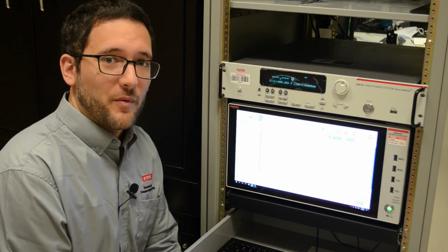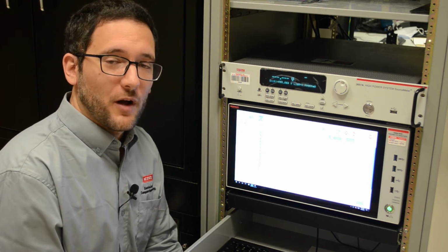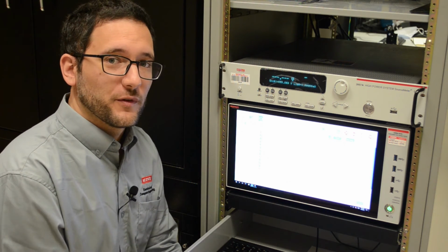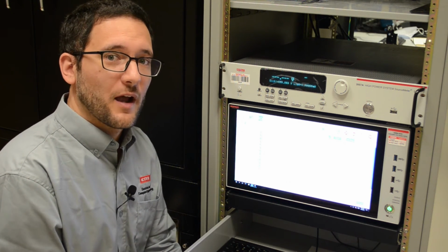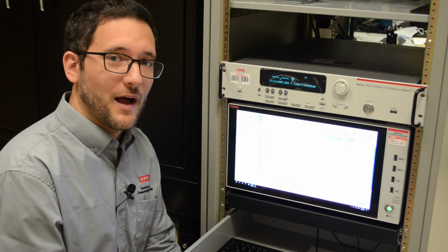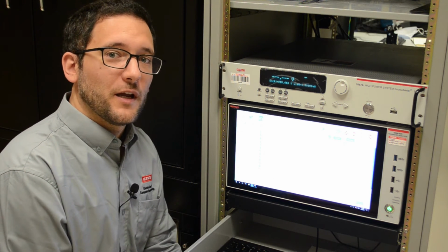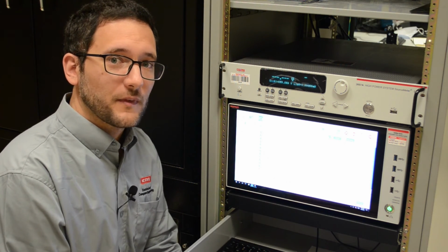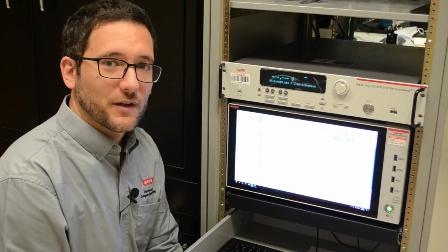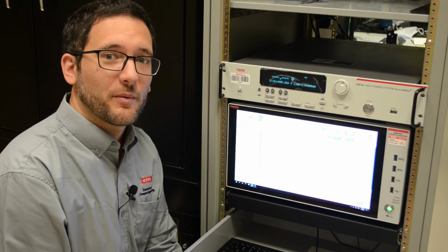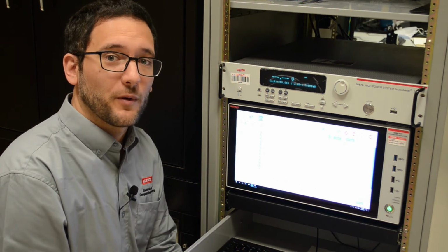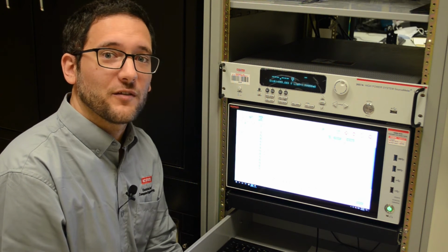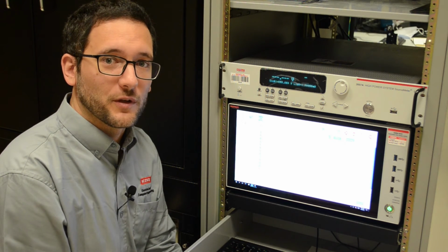Other semiconductor parameter analyzers provide modules that allow you to measure beyond 200 volts. In this particular case, such a module does not exist, so instead we have to rely on an external power supply to supply that larger voltage in order to test the limits of the breakdown voltage response of this type of device. The 2657 here is one example of such a power supply, and it's capable of providing a few thousand volts of bias while measuring very small currents needed to measure the off state of the device and indicate to you precisely when breakdown voltage will occur.